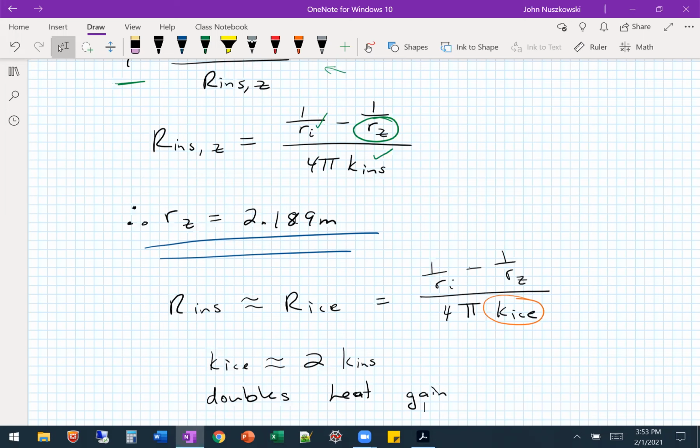So liquefying it allows for much smaller storage tanks. So we want to keep it in liquid form. With this higher heat gain, we'll try to transfer it more to vapor. We either have to put in energy to bring that vapor back to a liquid, or help by reducing this heat gain. Okay.